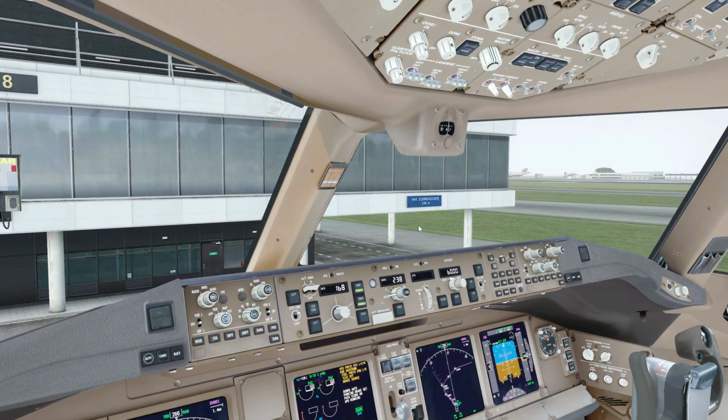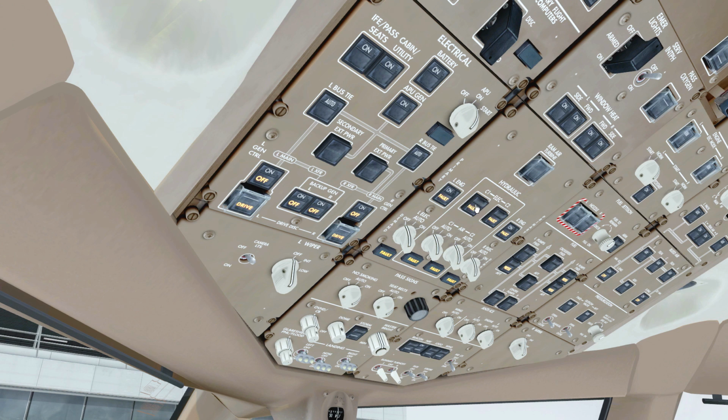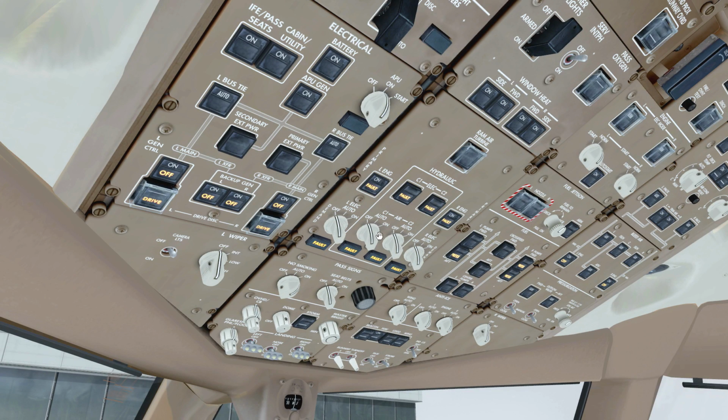If the bypass pin is inserted and if the ground crew has cleared you to start the hydraulics, you can just start the hydraulics. Now the way you start the hydraulics on the 777 is always a bit tricky, just like the 747 and I believe also the 767. You have to start the right demand hydraulic first before you start any of the other hydraulics. Otherwise there's a chance that hydraulic fluid is transferring from one system to the other, and you want to avoid that.